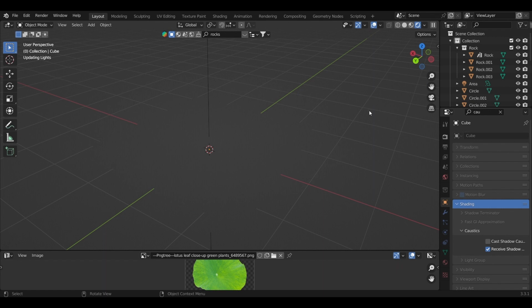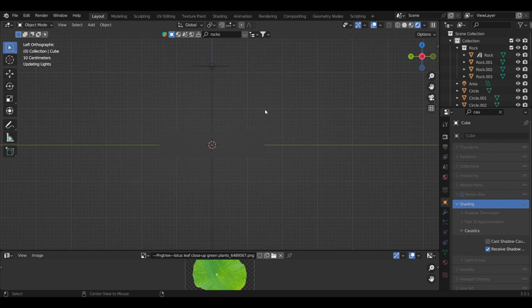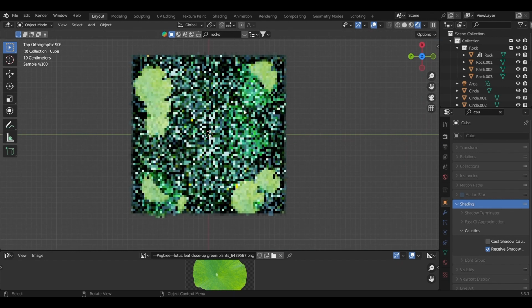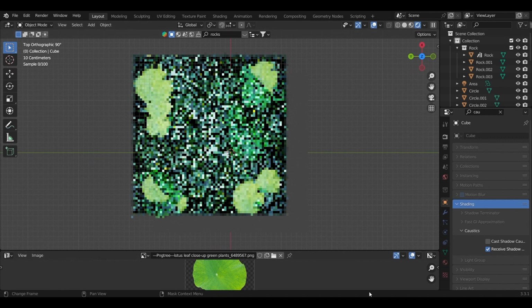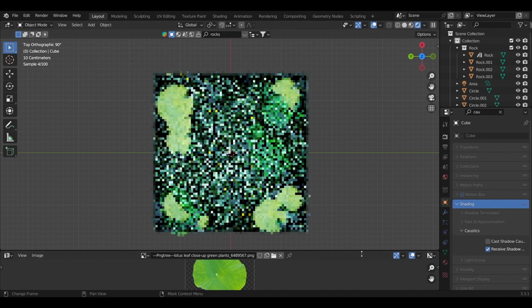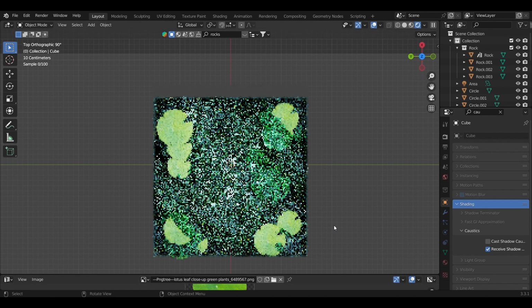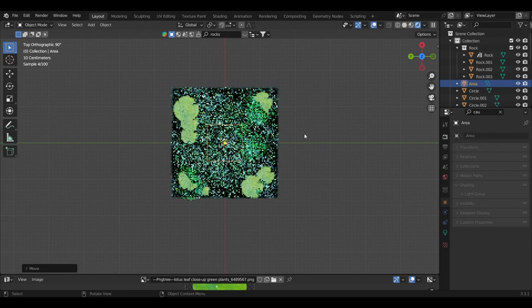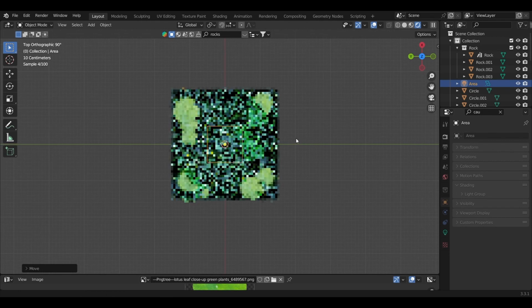Then you select the bottom part of the ocean, the ocean bed, go into the object properties and select receive caustics, the same way you added caustics to the top surface. That is what is going to give you that extra reality in the scene.